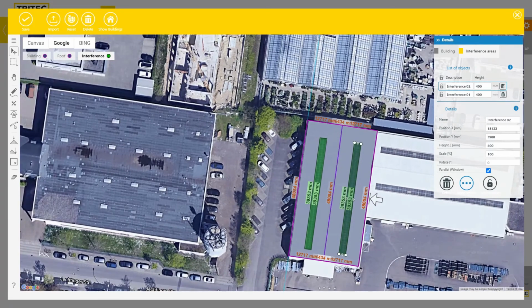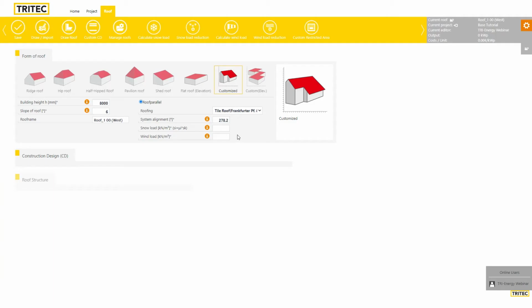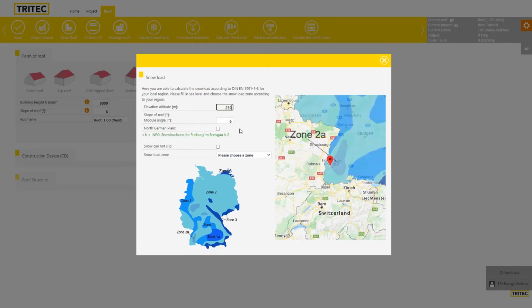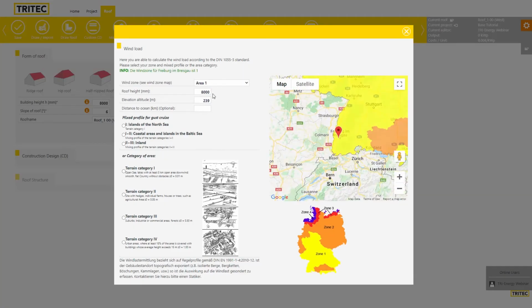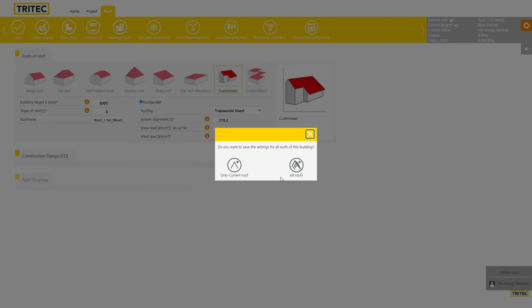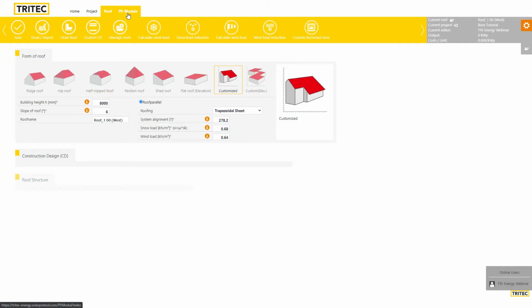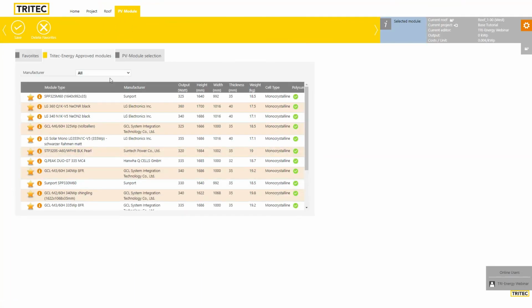I have the indicators for the lower part of the roof. Here's the ridge. I'm done. Everything is done. Very, very easy, very fast to do. Just hit save. Change the roofing. Snow load is, let's say, 2. And terrain category is 2. Hit save. All roofs, both sides, should be laid out, should be taken into regard.